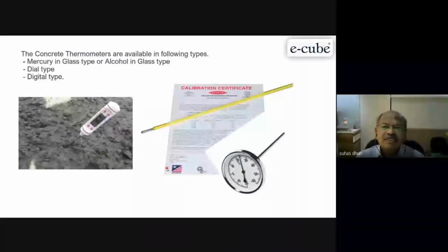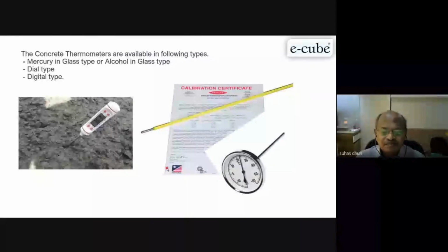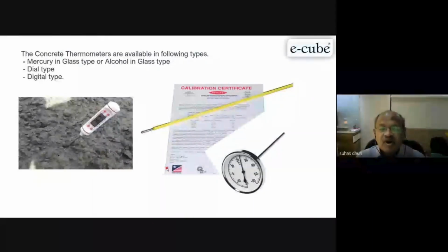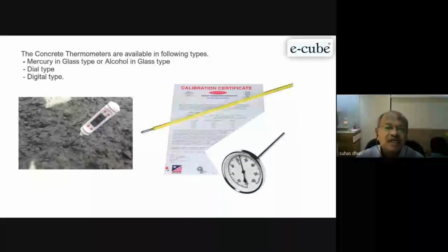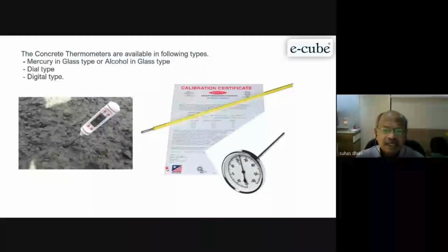See, for column it is maybe 140 plus minus 20. That depends upon what height you are placing the concrete. Sometimes we may require up to 160 also. And for slab, not more than 100, 80 to 100. And pile concrete maybe 150 plus.